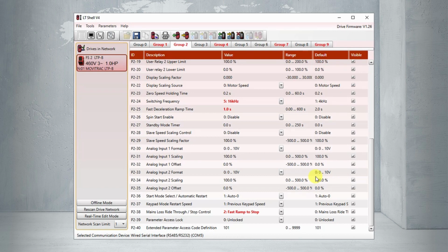Now what we're going to do is factory default our VFD. So we're going to reset it back to a clean slate. And in order to do this, I always recommend, first of all, disabling the VFD by turning digital input 1 off. And I'm going to also put it in controller inhibit mode. You don't have to do that, but I like to do it because it's kind of an extra safety layer. So I'll turn the 2 switches associated with my safe torque off inputs to the off position.